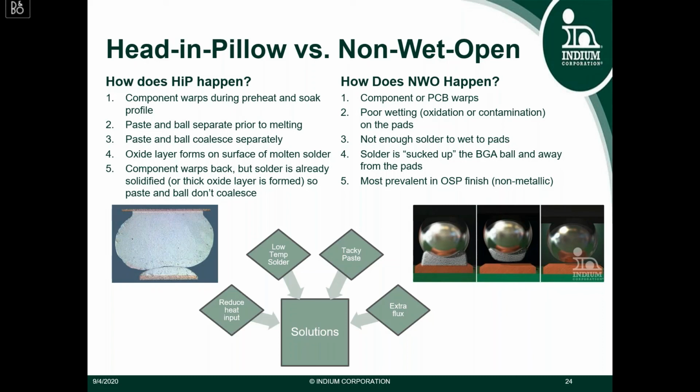Some solutions for this: you can reduce the heat input for your assembly. You can use a low temperature solder or low temperature profile.